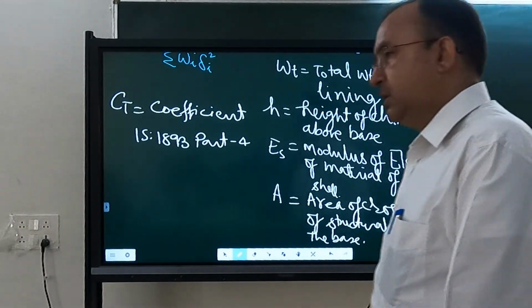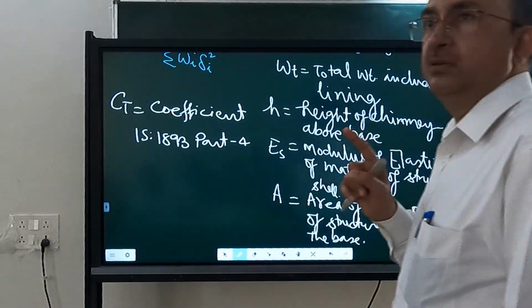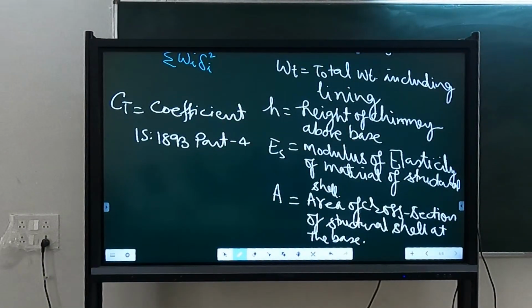If you look at the book by Yogendra, he has a chapter on damping, and there he has explained how the damping changes at different strain levels, up to epsilon y, the yield strain. Maximum damping we will get when our amplitude is epsilon y or larger than epsilon y. Larger than epsilon y, there are two components: one is the hysteretic and another one is the material. So we are talking about material damping only, not the hysteretic damping. That is taken care of separately.